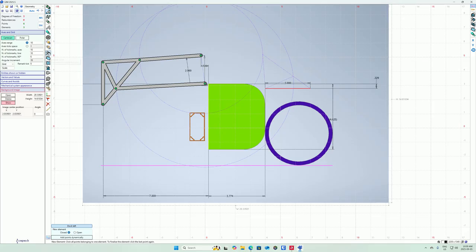And now I can break those up by putting in some revolute joints. So it has a bunch of different joints. I'm going to use the revolute joint here. See how it broke it up here. See how it broke it up. And then I'm also going to use it here to create two revolute joints.